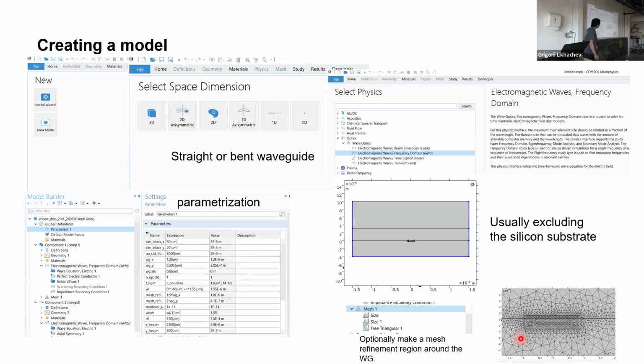Later, when you are setting up the model, maybe some of you already worked with parametric CAD tools, where you can do a parametric design. You first define your parameters in a separate sheet, and then you use these parameters to construct your actual model's geometry. That's an important concept that helps a lot when you later want to modify your geometry.